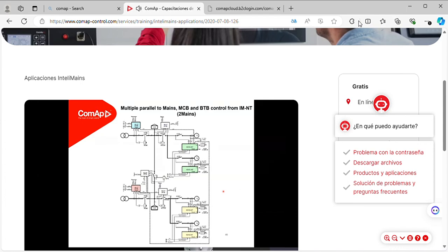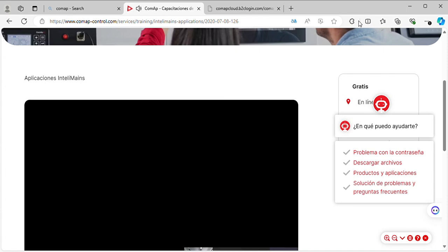This is the same, but the number of gensets on each cluster we can increase. So as you know, the magic number is 32 controllers, which can synchronize on the CAN bus. But if you have more than that, we can subcluster them using our bank controllers. But this is another illustration of each bank having more and more gensets. So that's mostly from my end.